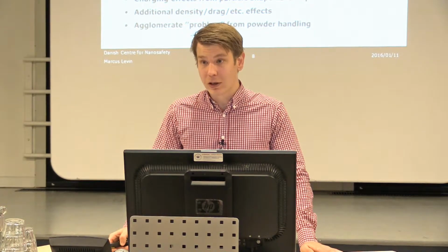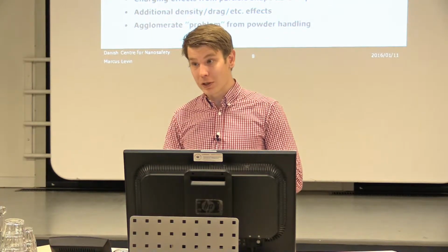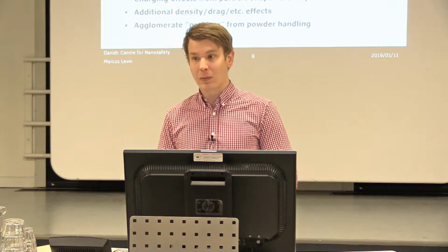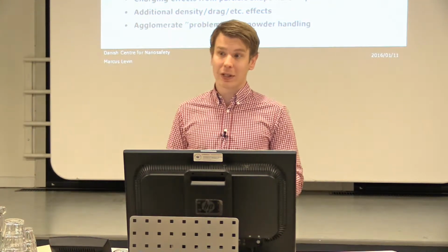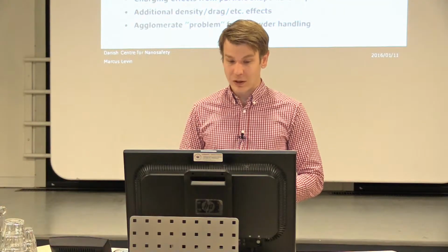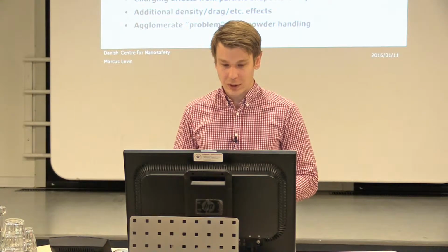And these non-spherical particles also affect a lot of things, such as the charging of the particles. We have this nice relationship, as I said, when we precondition them, but if they're not spherical, then this relationship will strongly change, so we will not get the response that we wanted to get. And then there's also a lot of effect on drag and so forth on the particles.